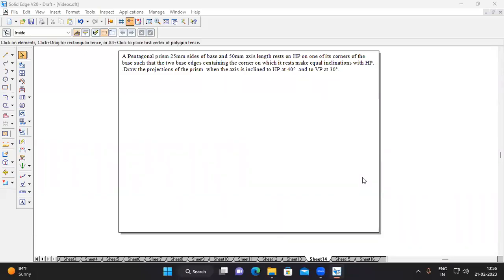Hi, I am Mohan. In this video session, let us solve one problem of prism, pentagonal prism. The problem is like this: a pentagonal prism, 25 mm sides of base and 50 mm axis length rests on HP on one of its corners of the base, such that the two base edges containing the corner on which it rests make equal inclination with HP.